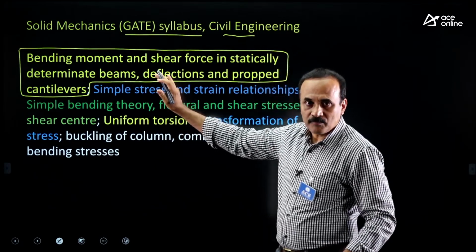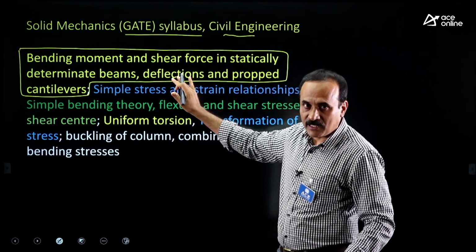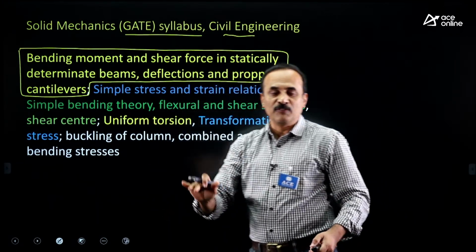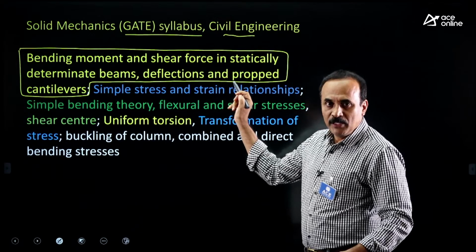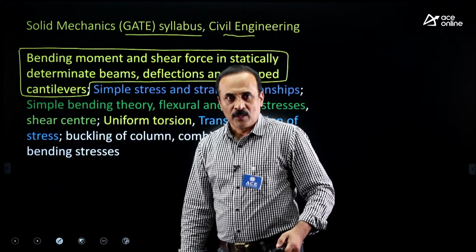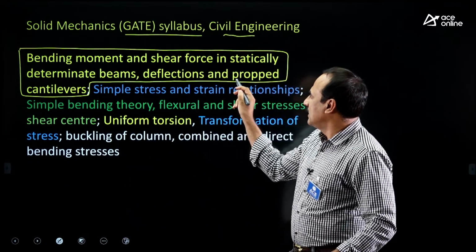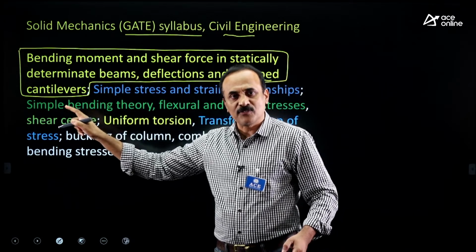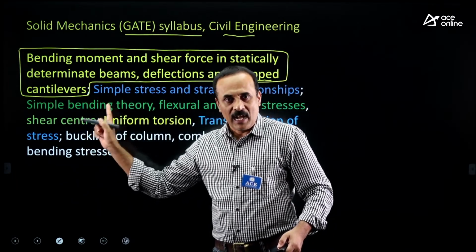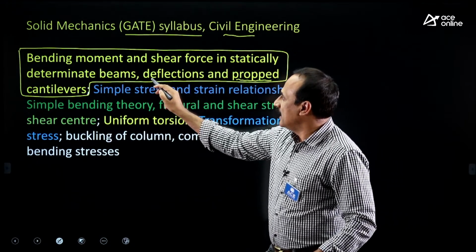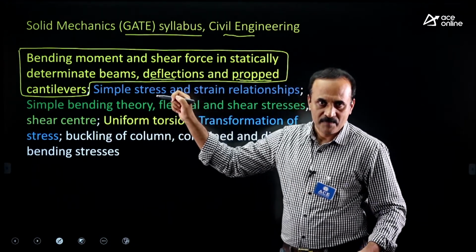And then deflection standard cases also you need to learn by rote, because those deflection equations may be used as compatibility for your propped cantilevers. So most probably there is a high chance of getting a question on propped cantilevers from the civil point of view. And those propped cantilevers you can analyze by the basic deflection formulae.